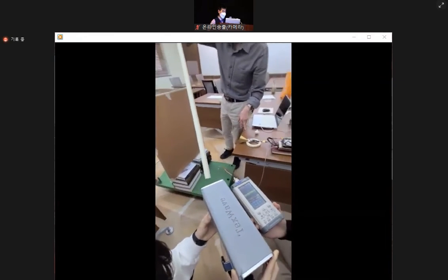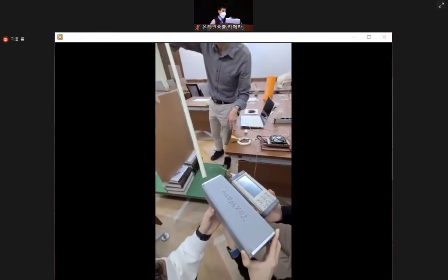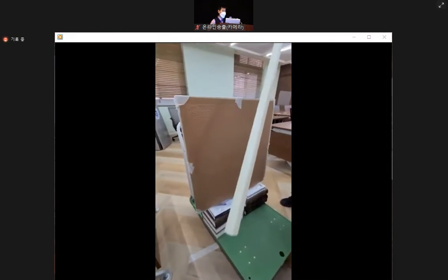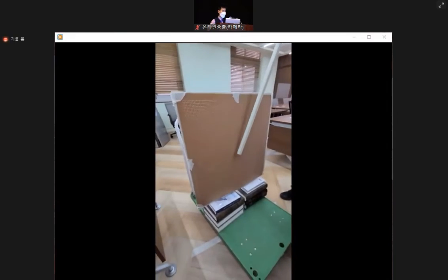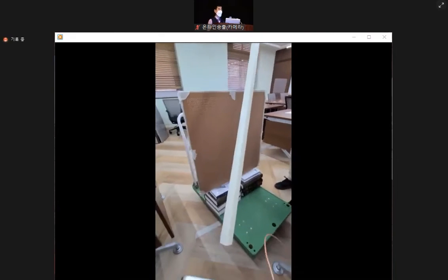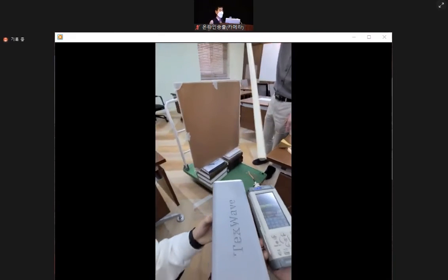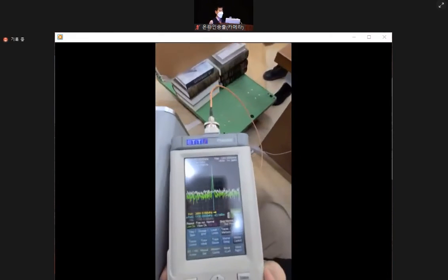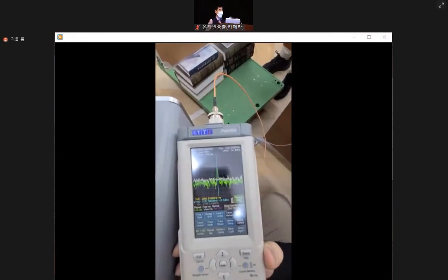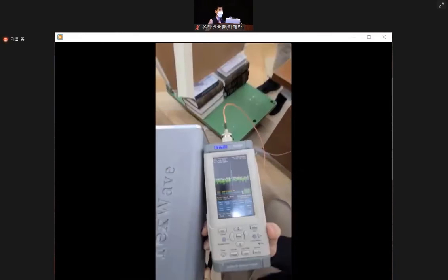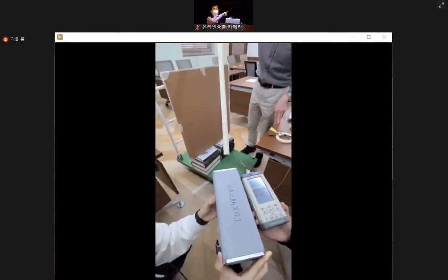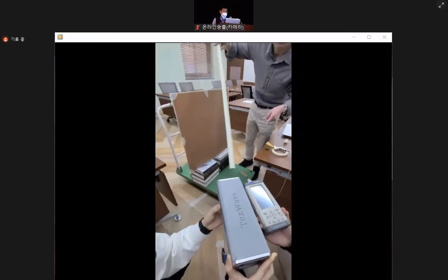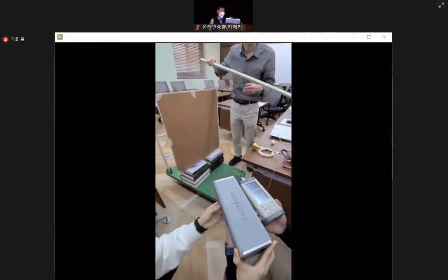Now it is positioned at the angular position of 41 degrees. If you extend the line from the center of the metasurface, this is 41 or 45 degrees. So minus 41 dBm is read there. You see a spike there? This is hopefully the strongest point. That means, at that angular position, or in the azimuth plane, there is a certain value of strength.